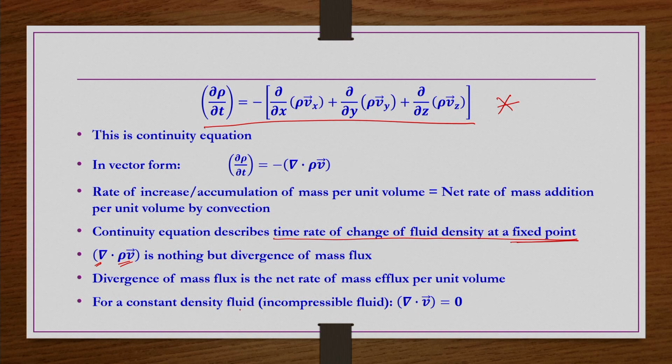And then for a fluid of constant density, we can write the same continuity equation as del dot v is equal to 0, right. So, now this is about the continuity equation derivation in rectangular coordinates. We can do the same thing in cylindrical coordinates, and in spherical coordinates, and accordingly develop the equation of continuity in cylindrical and spherical coordinates as well.